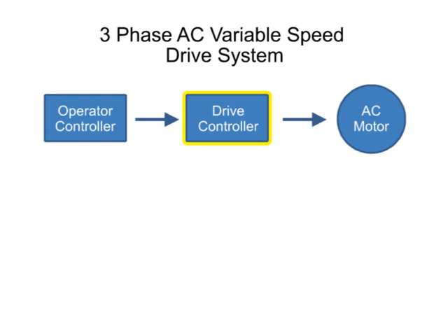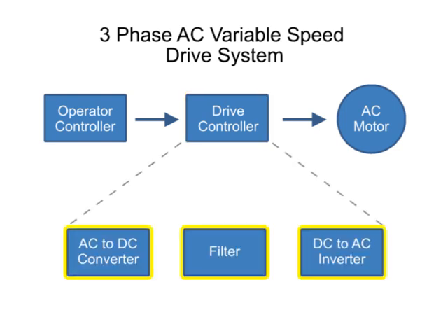The drive controller consists of a variety of components that work together to convert an AC input into a frequency and voltage output necessary to change the speed of an AC motor. Let's look more closely at the components of the drive controller.